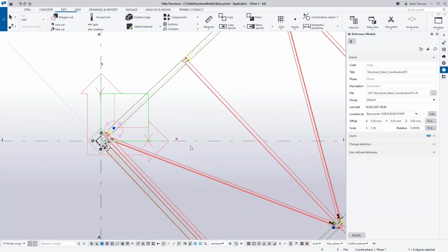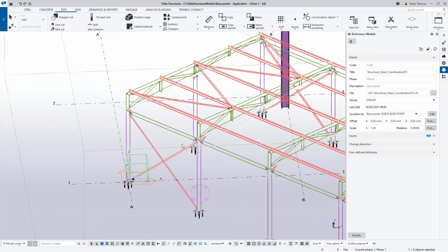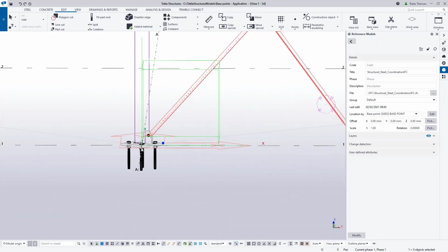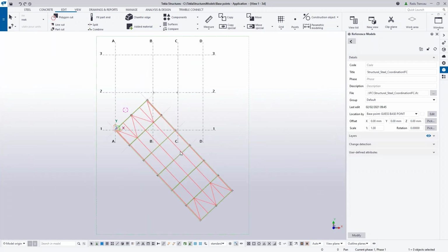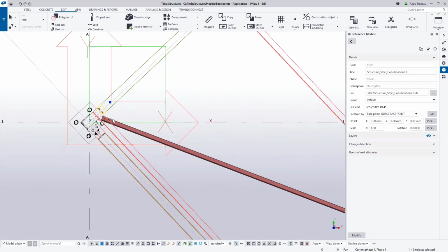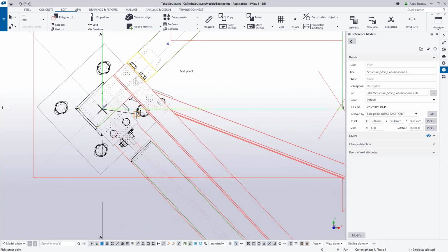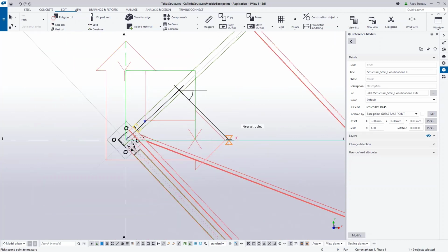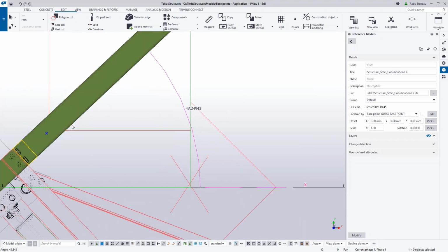So that's a way of working out the XYZ. Obviously, if the IFC sits above or below, you will always follow the same logic by just picking yourself a reference point. Now, with the actual angles, that's just purely an exercise of measuring what's the angle on which the IFC is rotated. So you will have to do this guessing work now.